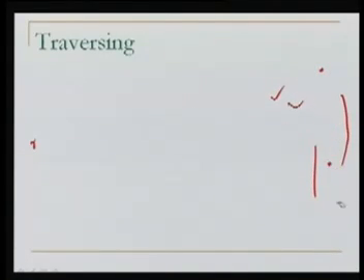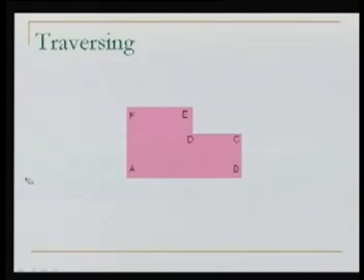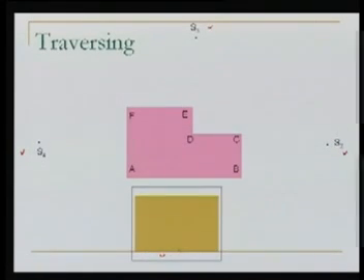We will see one example of traversing now, how we plot in traversing. We have taken a building here, and these are the corners. We occupy, let us say, point S1, and we have also decided that after S1 I will occupy S2, then S3, and then S4, and I can cover this entire building. We keep our plane table here, this small s1, because my plane table is over the ground point S1.